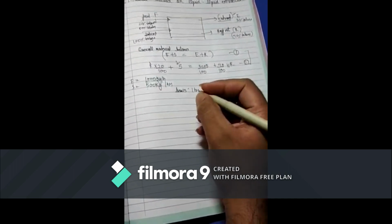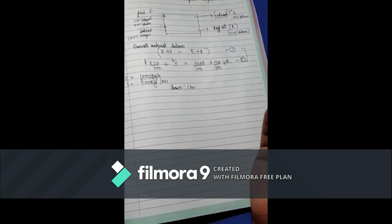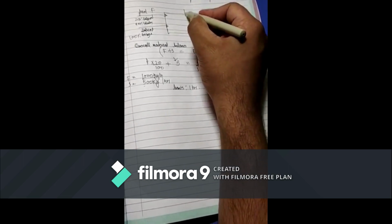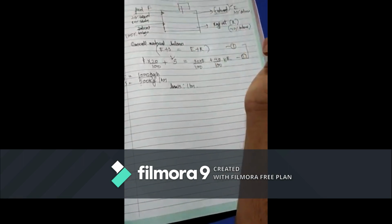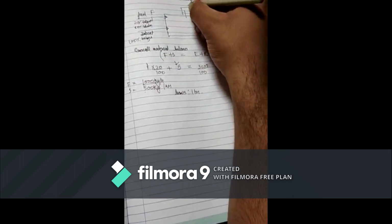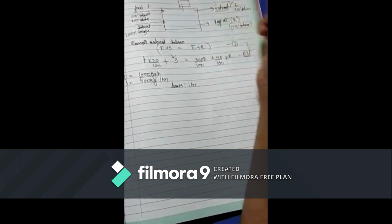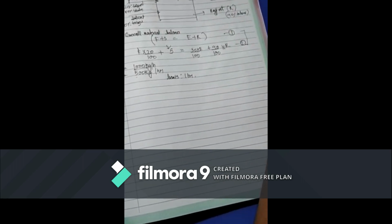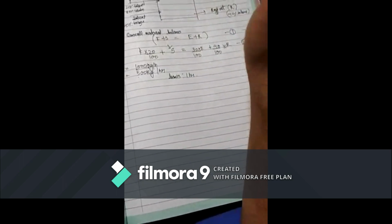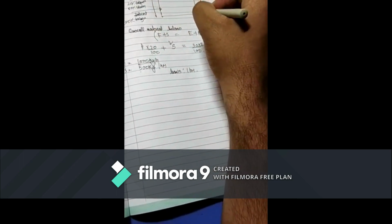So the principle of this question was to clear your concept. Now suppose the question is a bit tricky and they give you an evaporator in this same question, and the evaporator removes some water from this equipment. It will remove some water definitely, right? Suppose it removes water W. Now if the question comes in this way, don't get confused. Your concept is the same, overall material balance. You'll include the evaporator in your system as well.